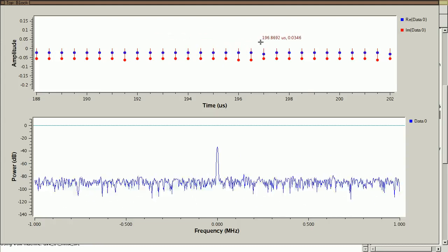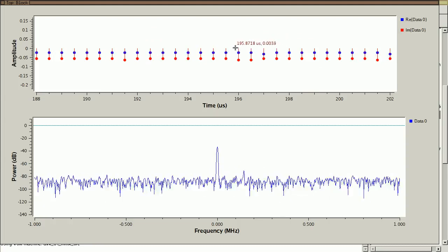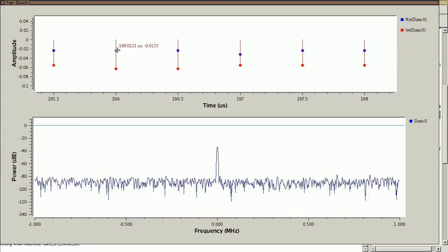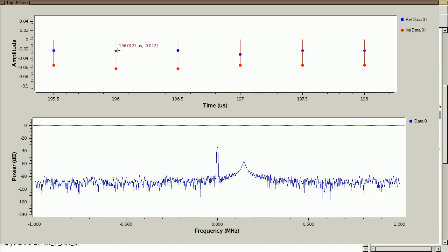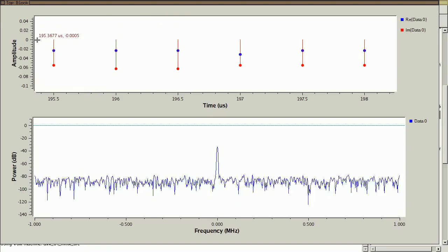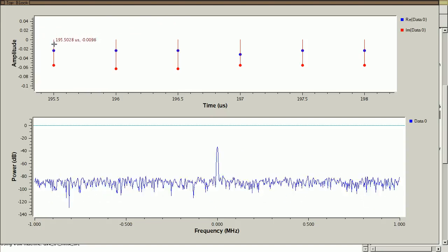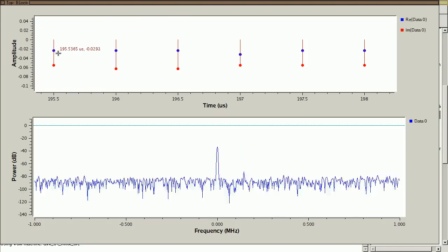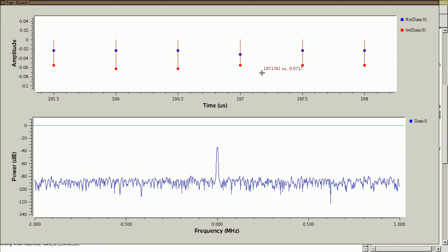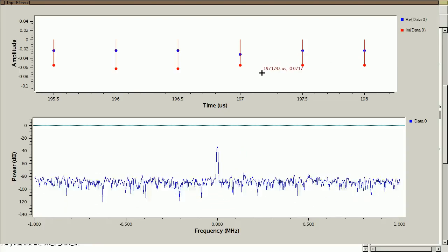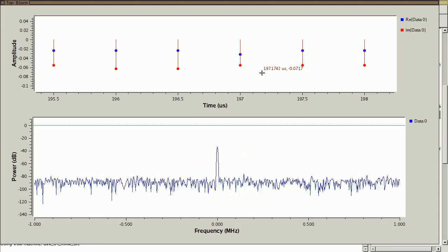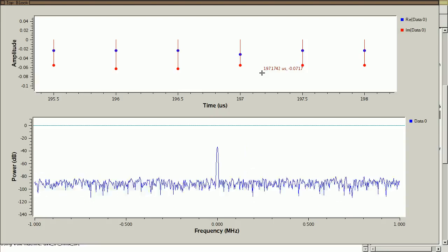There are just a few very distinct values that have samples assigned to them. So you can actually see, and if we were to scale these up by 256, you would see that these are integers. So for example, this might be 0, and this might be a negative 1, and then this dot would be at negative 2, and so forth. What we're seeing is that very little of our dynamic range is being used, and we could actually amplify our signal in the digital domain.